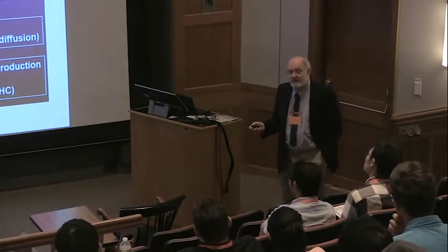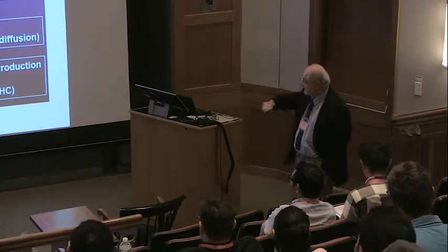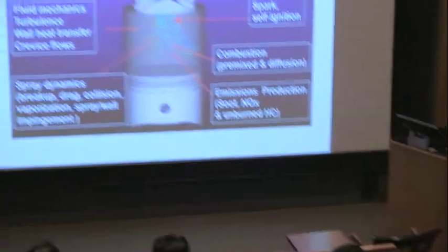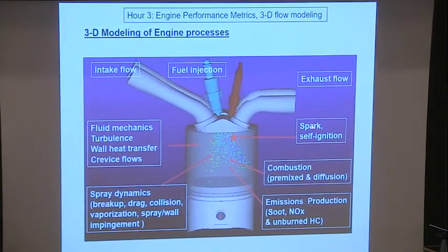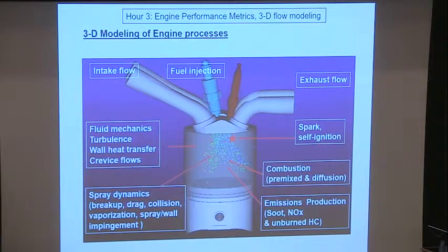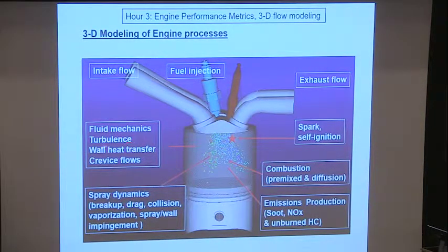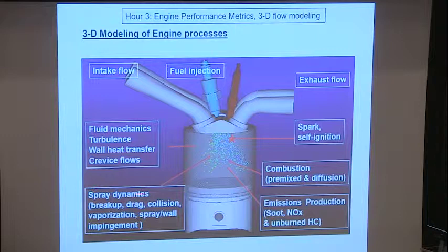Real engines are much more complicated. Okay, so we have intake flow, we have fuel injection, exhaust flow, we have spark ignition, or in diesel, self-ignition. We've got fluid mechanics to worry about: turbulence, wall heat transfer, crevice flows, the flow escaping past the pistons, spray dynamics, combustion, either premixed or diffusion, emission. So lots of things that we need to look at.